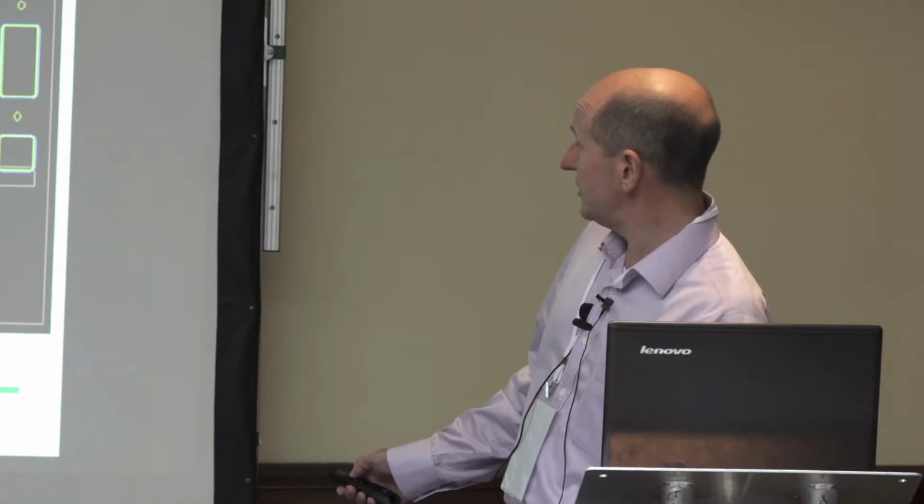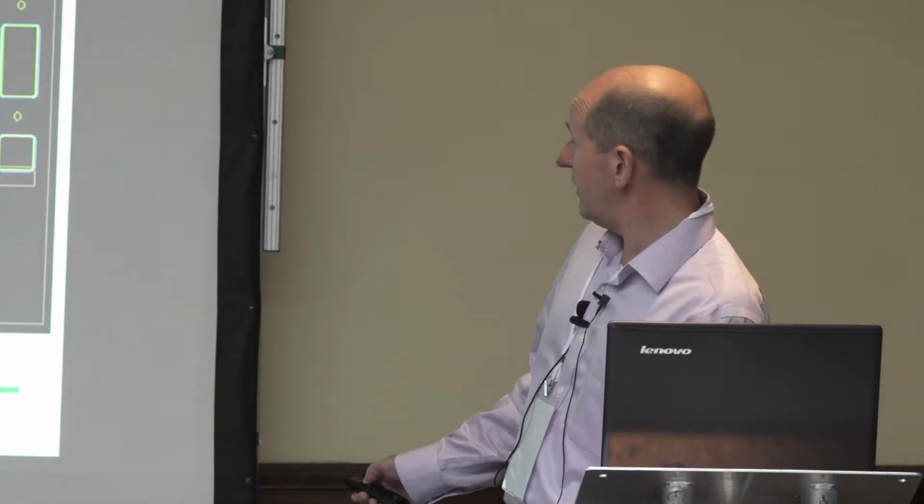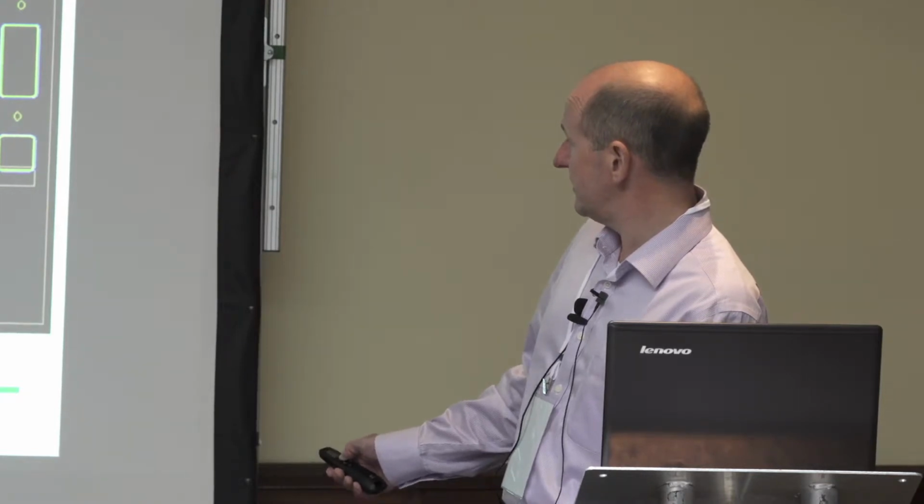We have the driver stage, which we split here, and we've got low-pass LC matching. These are capacitors, these are vias, these little ellipses. And ultimately, we need to EM simulate this. It costs a lot to make ICs, and people like them to be right without having 6 or 7 runs. Ideally, we like them right the first time.